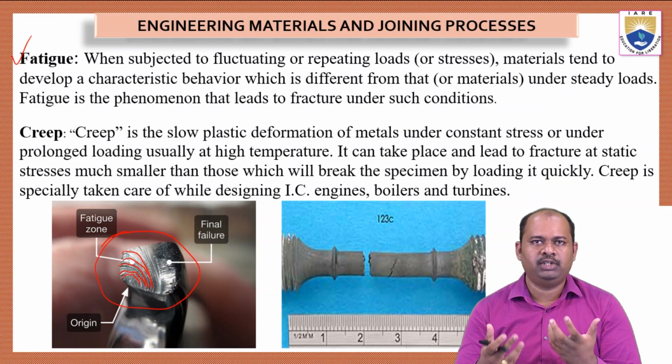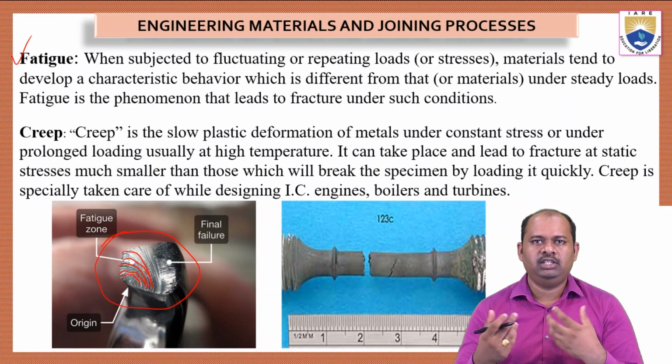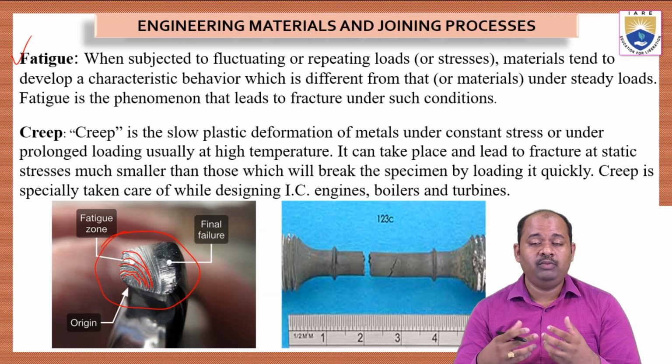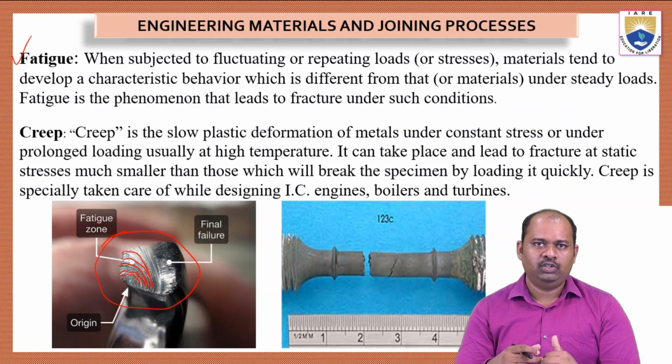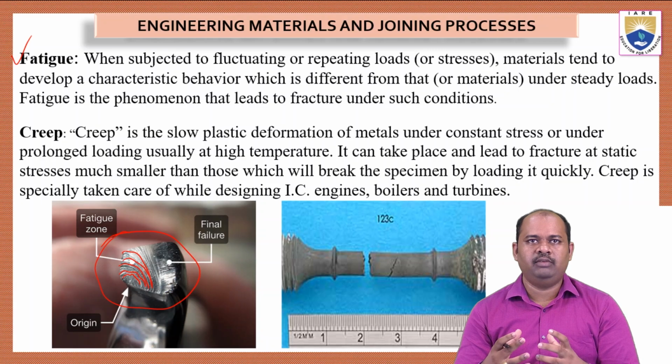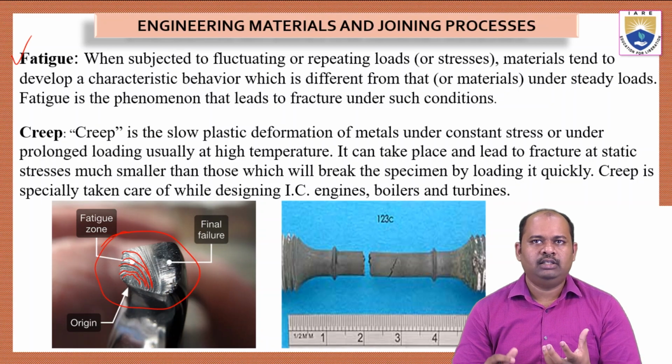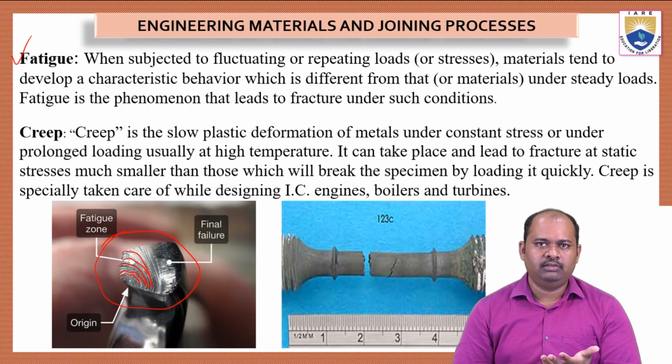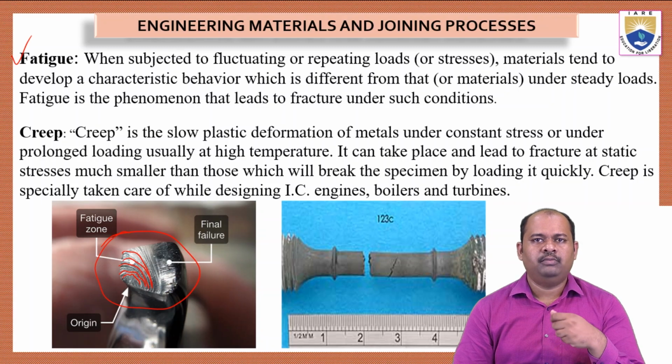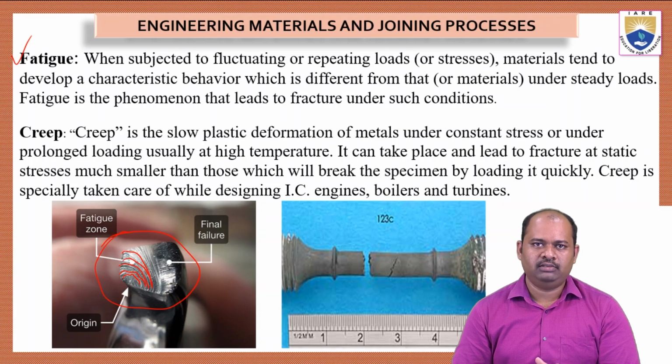That means it is being subjected to fatigue. So whenever this fatigue happens, the body will break or fail at a value very much less than its actual strength. That is why fatigue is a very bad property. We have to understand that the body should not be loaded cyclically or repeatedly, which will break the body at a much smaller load than the actual weight bearing capacity.